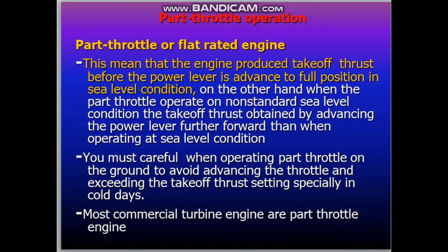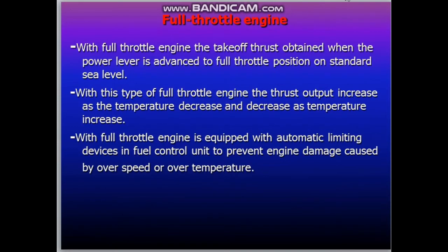Most commercial turbine engines are part throttle, full throttle engines. With a full throttle engine, the takeoff thrust is obtained when the power lever is advanced to full throttle position on standard sea level. That means the engine will arrive at the takeoff thrust when the lever, or our throttle, arrives at the full position.